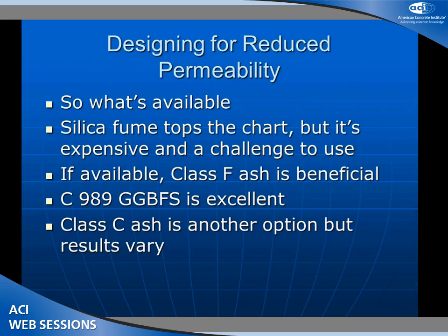We do have silica fume. It tops the chart for densifying concrete. But it's expensive, and it's a challenge. We've had projects so big that we actually installed silos specifically to carry silica fume. 200,000 yards will buy a silo.